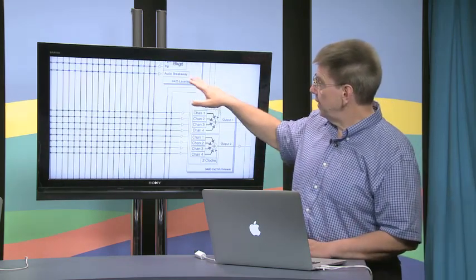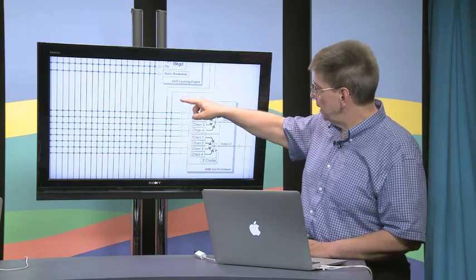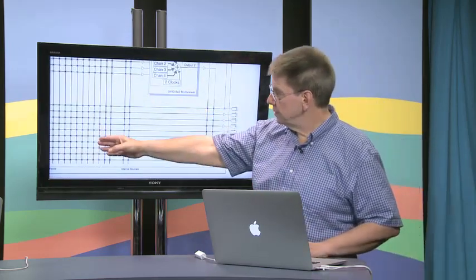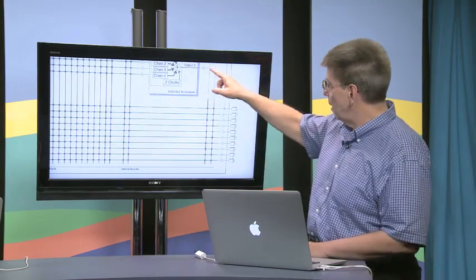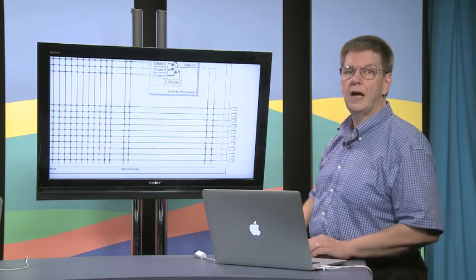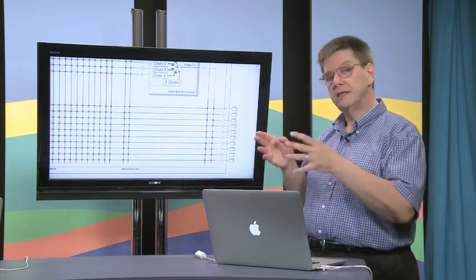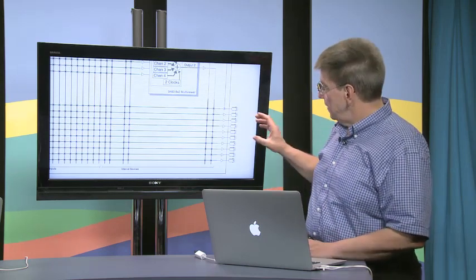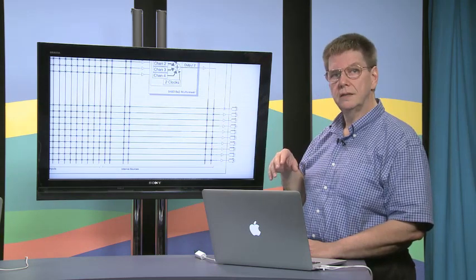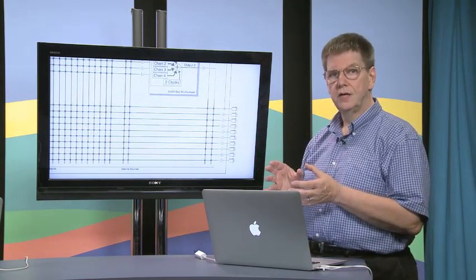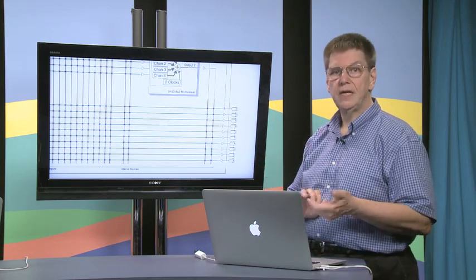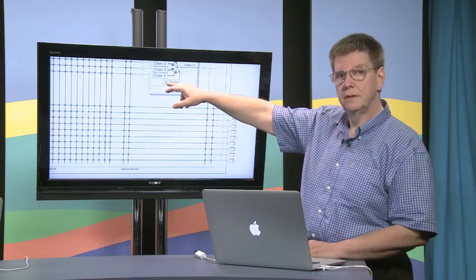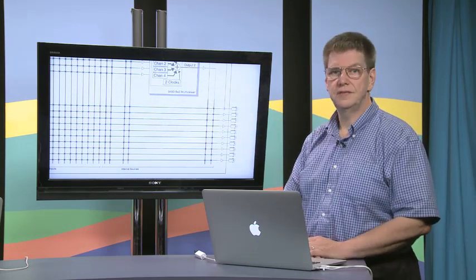Furthermore, if, for example, the layering engine was a part of this system, then the outputs of the layering engine are also available as inputs into the Multiviewer. And then finally, all of the original sources, the layering engine sources, and the outputs of the Multiviewer are then routable to any output of the router. That means that any output of the router can deliver Multiviewer or any one of the other sources to a monitor, to an encoder, to a display. And this flexibility in how sources are handled within the routing architecture translates into a lot of power in your facility. It means, for example, it supports an important feature that lets the operator choose a particular cell in the Multiviewer and route it directly to the output they're looking at for QC monitoring.